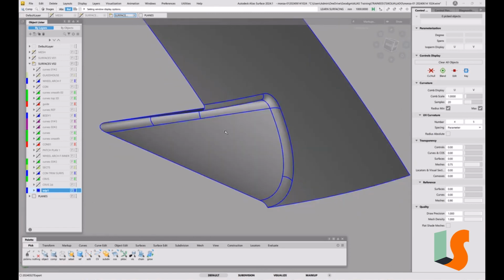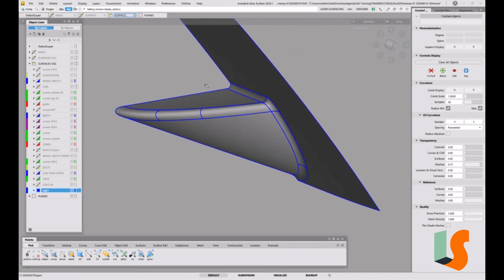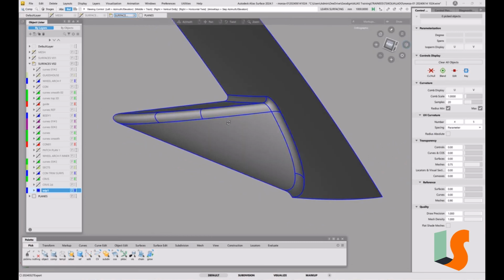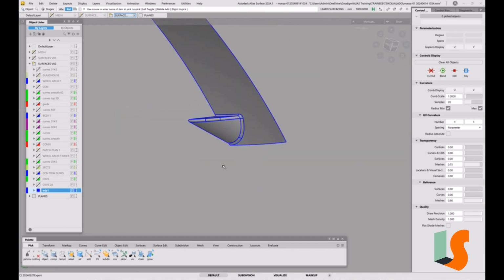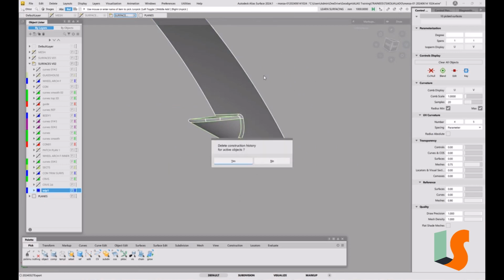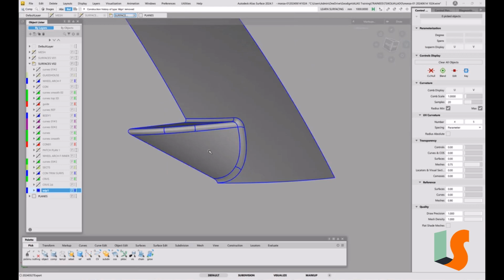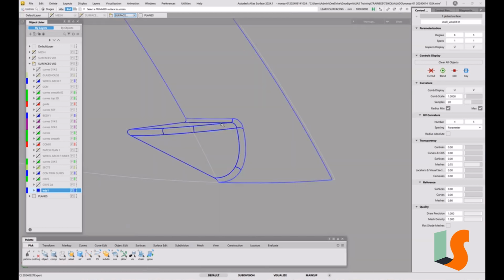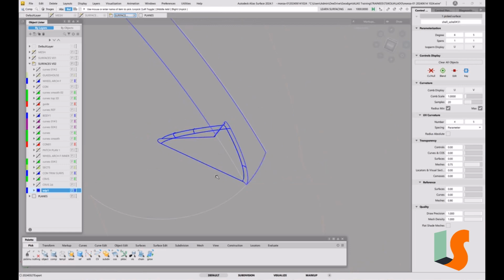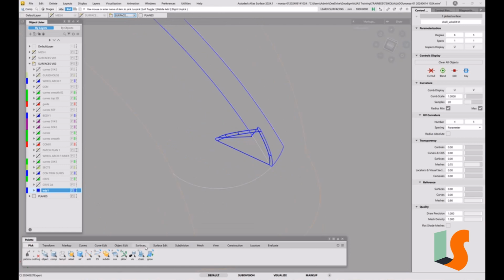And the easiest thing to do there would just be to put in a blank surface, so you could just shade that up as a mesh, or just make it black or whatever. The other thing I noticed is I've got history on, so let's get rid of that, because once you've finished an area, you always want to delete all of the history before it causes chaos. I'm going to just do Control-C, Control-V on that, and then untrim that one, and then we'll offset that, and I'll take it back to some point down here so that we can block that off in a sort of sensible way, or semi-sensible way.